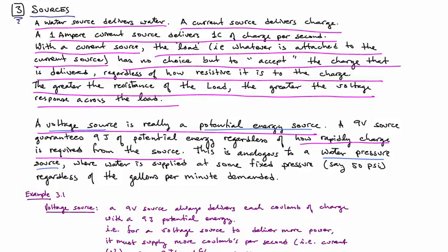Even so, if you stop the flow and put a pressure gauge on your water hose, you would measure 50 psi, whether you measured it there or back at the spigot. As long as there's no water flow, it'd still be 50 psi. But once water starts flowing, that pressure drops.